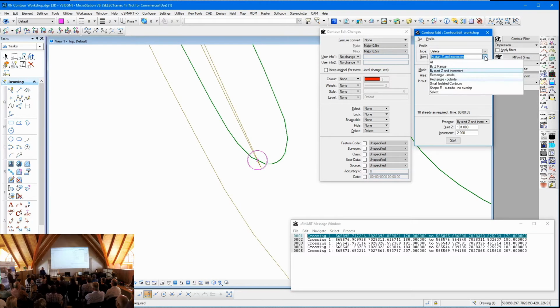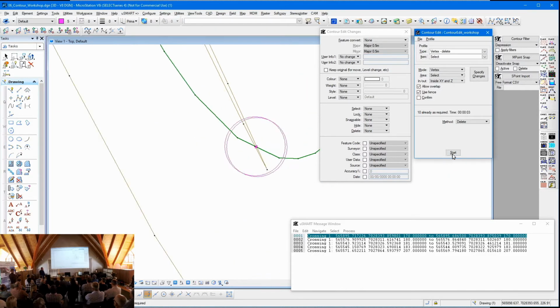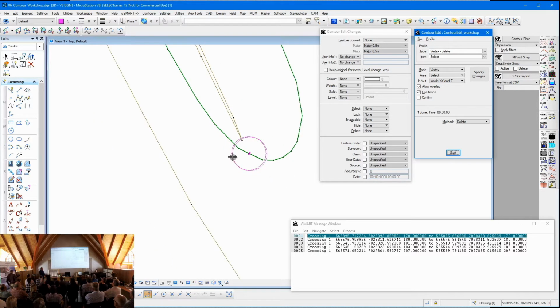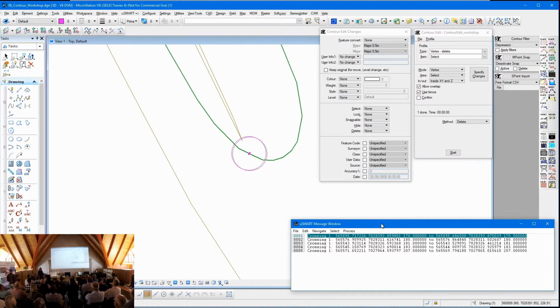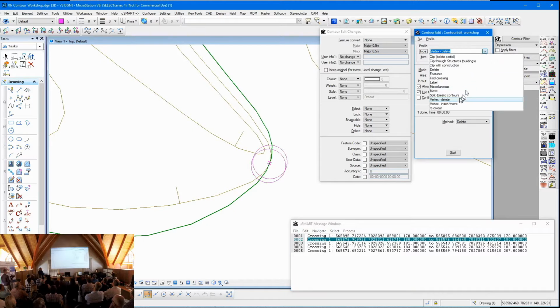Because this happens so often, these circles are very dynamic. They switch on, and they disappear when you fix the problem. This is currently just displaying it, and you just clean up the data afterwards. So you might decide there's obviously a serious problem there. We're going to delete that node. And if you want to move on to the next one, she simply presses F7 over here, and using the coordinates there, it's now finding that area.